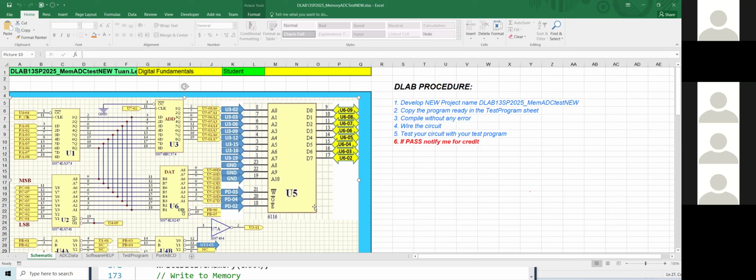However, remember, when you're reading data out of the memory, pin 21 must be 1, pin 20 has to be 0, and enable can be 0. You don't have to go 1 to 0 to 1. The thing is, now data just goes out. It cannot come in. So depending on your address, data will be coming out. That is the way any memory will work.